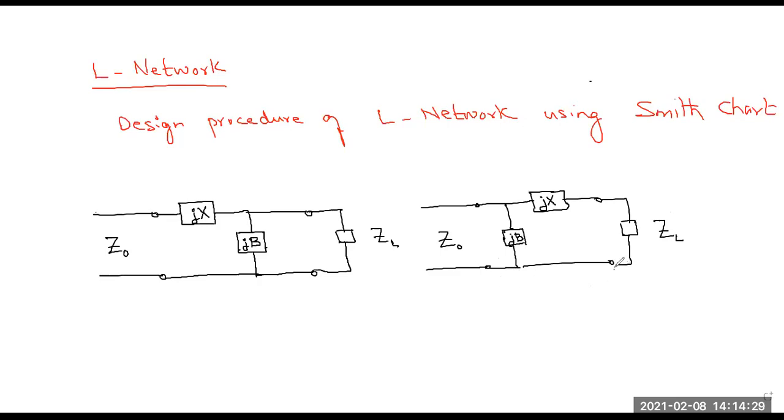This is something which we have covered, and I have already mentioned that whenever we connect any element, whether capacitor or inductor, in series with this transmission line, we represent that element by its reactance. And whenever we connect any reactive element in parallel or shunt configuration, we represent that element by its susceptance. So this is the susceptance of the reactive element, and this is the reactance of the reactive element.